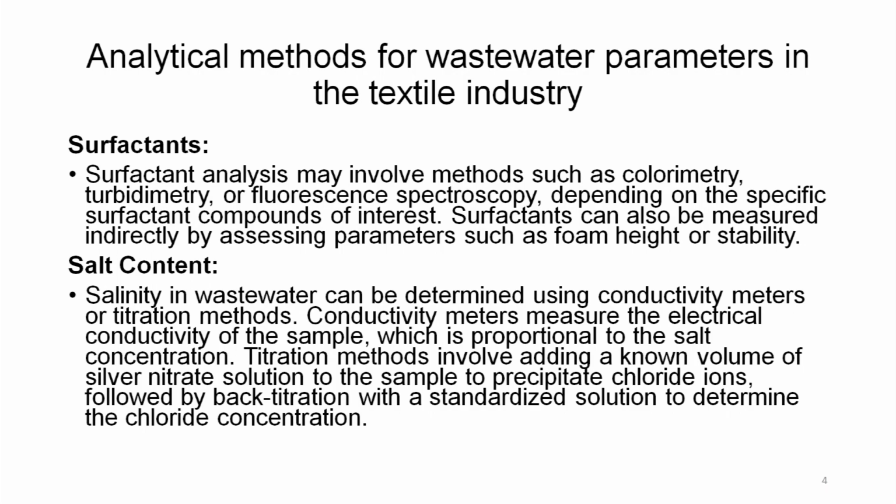Conductivity meters measure the electrical conductivity of the sample, which is proportional to the salt concentration. Titration methods involve adding a known volume of silver nitrate solution to the sample to precipitate chloride ions, followed by back titration with a standardized solution to determine the chloride concentration.